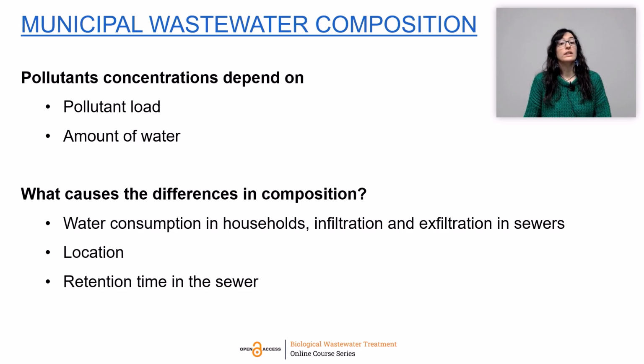And of course, the composition of the municipal wastewater changes significantly from one location to another, and it will also change over time as well. The differences in composition will depend not only on the consumption habits, so what we have just discussed, but also on the specific location of the households and also the retention time in the sewer. And other processes, such as infiltration and exfiltration of water during transport, will also affect the composition.